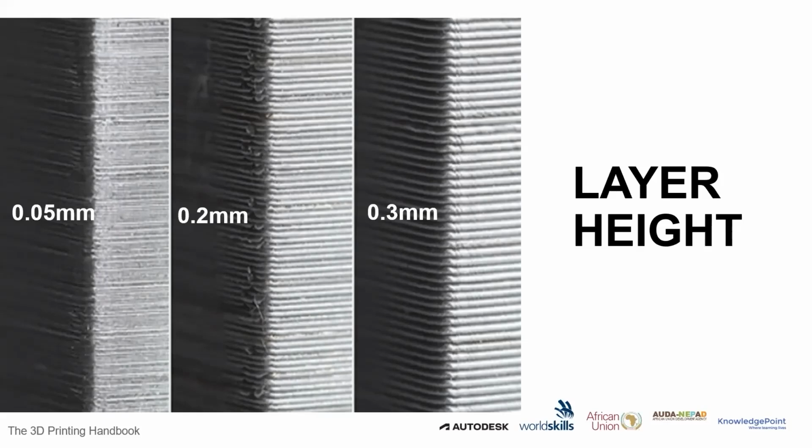And it's also very important that the relationship between print time and layer height is linear. It means that when your layer height is increasing, your printing time is decreasing, but your surface finish is getting rougher, not finer. You're also probably going to have issues printing tiny details in your parts. But when your layer height is decreasing, your printing time will increase, but that also gives you finer details. So it really is something you need to know: when to use which and how to use which. It's very, very important. We'll also talk about that.